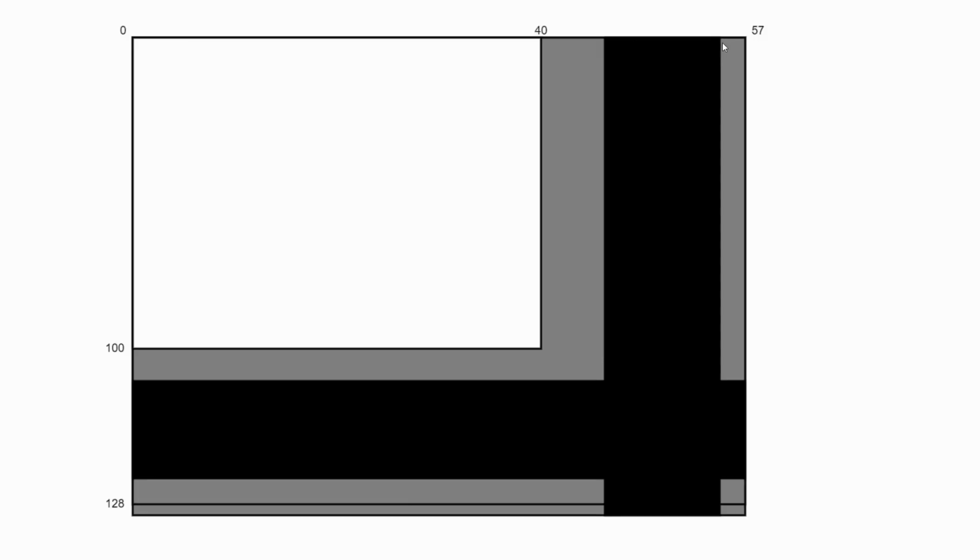And finally, once it's back on the left-hand side, it'll start drawing the left-hand border region, which again is in the background color. Only then is it ready to start displaying the next visible scan line, and it'll be back in the active region displaying pixels again. And just repeat this procedure until it gets to the bottom of the active region.